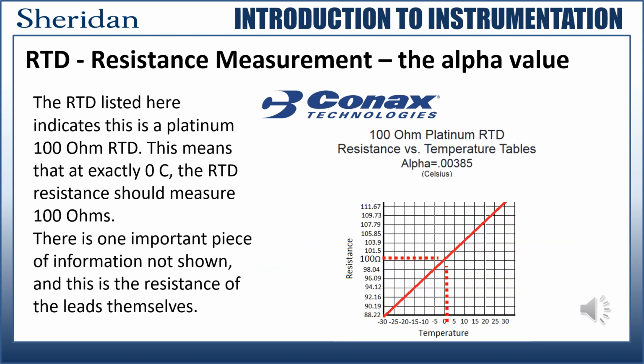The RTD listed here indicates this is a platinum 100 ohm RTD. This means that at exactly 0 Celsius, the RTD resistance should measure 100 ohms. There's one piece of information not shown in any of the forms, and this is the resistance of the lead wires themselves. This will be important when working on the lab.